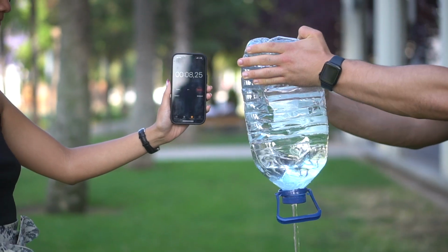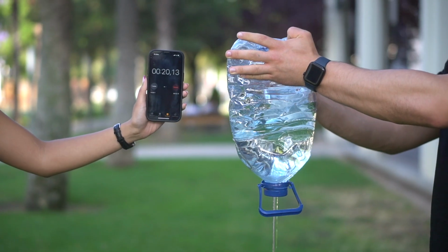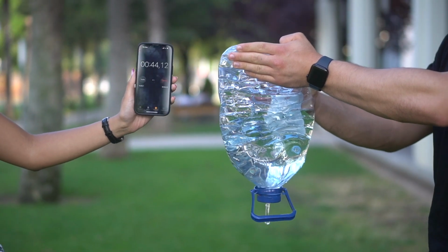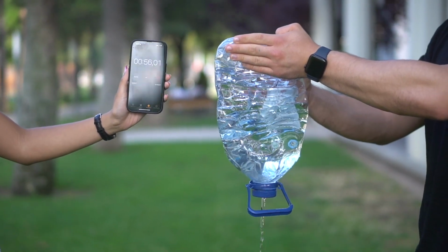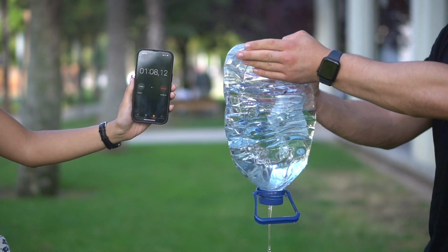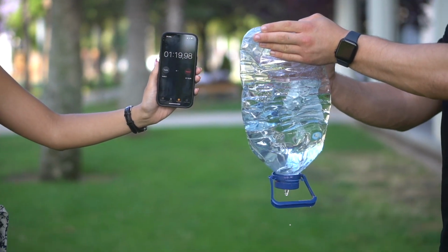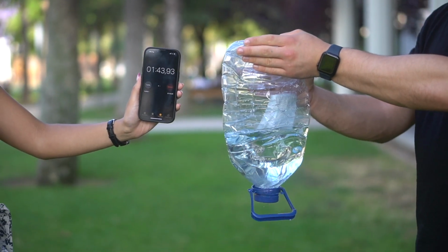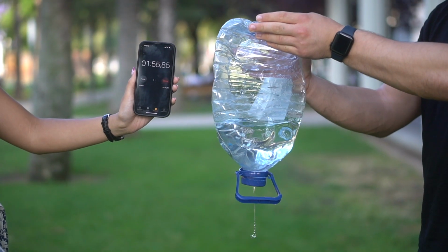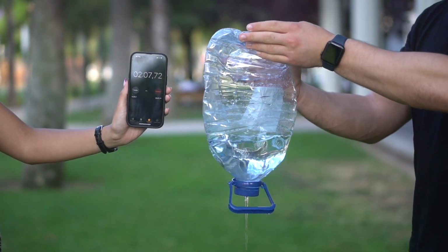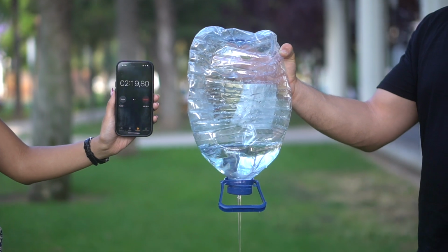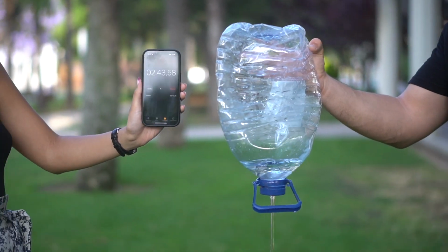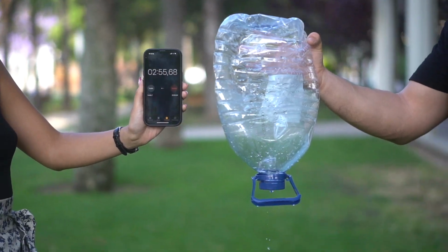Lastly, we tested the drainage time through the 10 mm hole, but without any nozzle or pressure equalizing tube. This test was conducted to verify whether our fitting was actually necessary to improve drainage performance. We observed that the total drainage time for this setup was nearly 3 minutes. The absence of pressure equalization caused significant compression of the container and introduced uncontrolled bubbling into the system. In comparison to the nozzle setups, which drained in approximately 1 minute and 50 seconds, this configuration was about 1 minute and 10 seconds slower, demonstrating the clear advantage of using the pressure equalizing fitting.